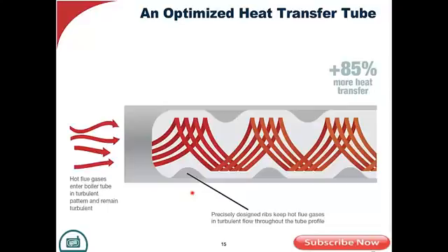So that's all the technical jargon that goes on, but essentially all I'm trying to do is break that gas up so I've got good contact with all surfaces on the heat transfer side of that tube to get it into the water. And as a result, what I can do is reduce the heat transfer surface by as much as 85%. And why do I want to do that? Well, I can put more energy into the furnace, number one, reduce the convection section, and reduce the overall size of this, let's say, horizontal fire tube boiler. That's why the industry is beginning to gravitate in that direction.